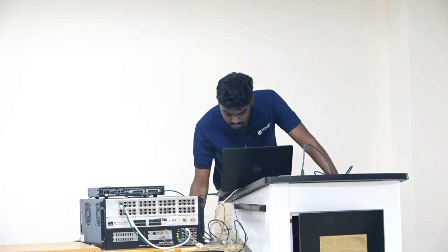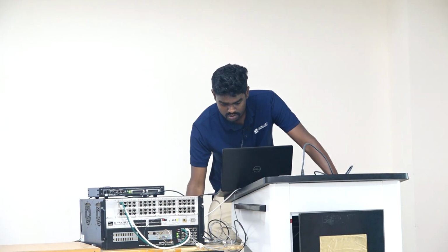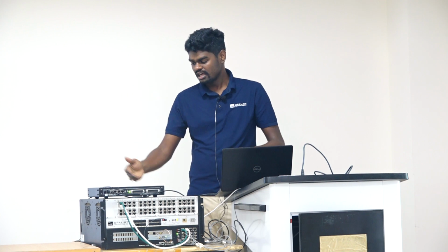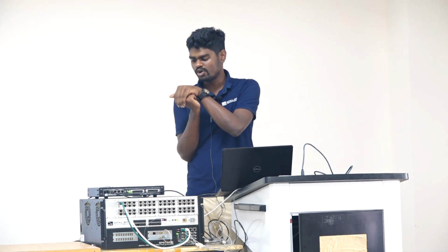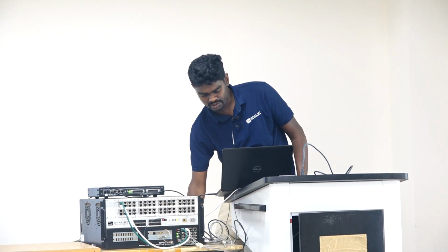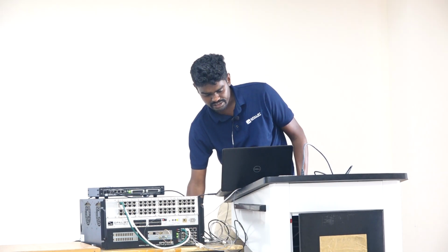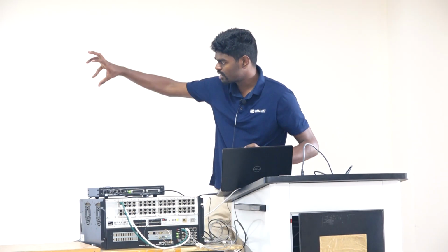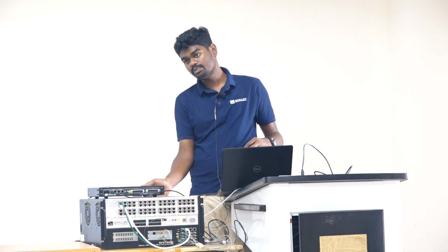I am adding the current and voltage measurements in the model, and you still need to do some signal conditioning, because our analog output can send only plus or minus 16 volts, and this controller can take plus or minus 10 volts for the feedback. So accordingly, you do the signal conditioning here and send it to the analog output. Here we have this analog output block, which helps you to configure the analog output you have in the simulator.